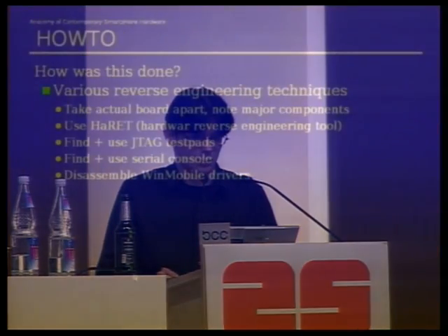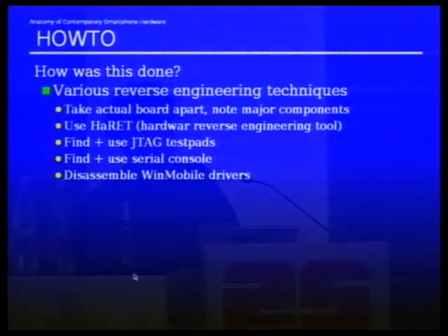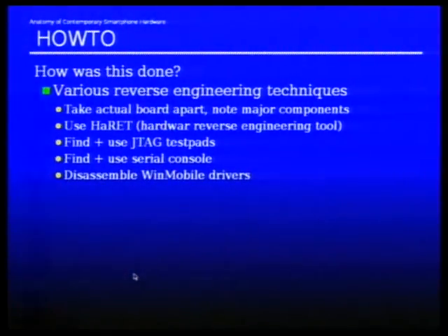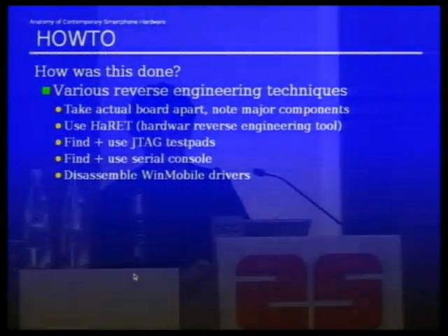So I started this project, the status of the project you can check somewhere else. So the question is, how does one go about understanding more of the various hardware in those systems? Well, basically you have a number of different approaches. Number one is take the actual board apart, take notes of the major components, and see if you can find anything, like Google for the identifiers on top of the components, try to get the data sheets, and try to put together how the device works.